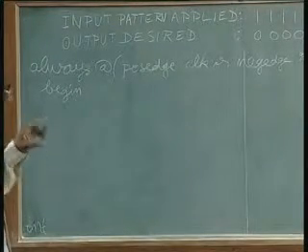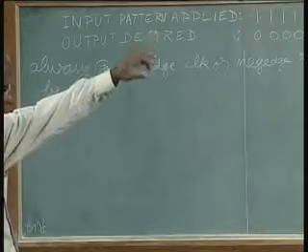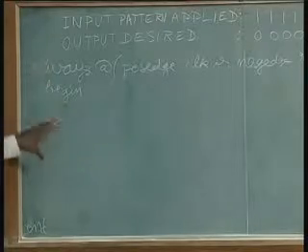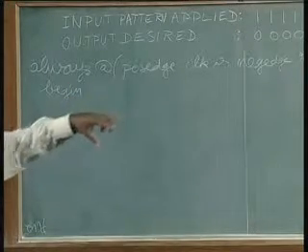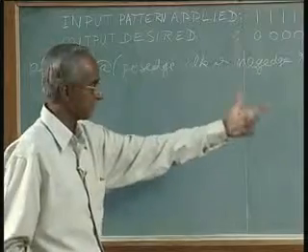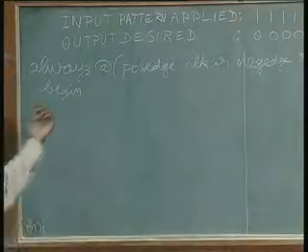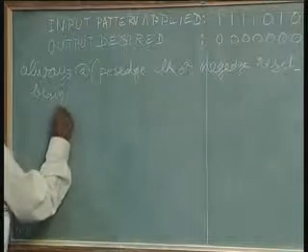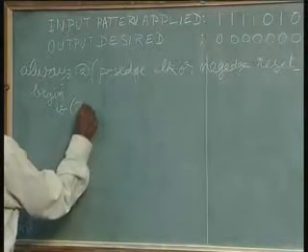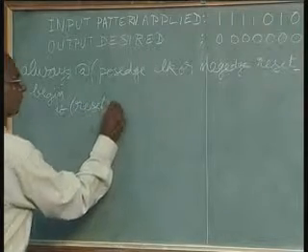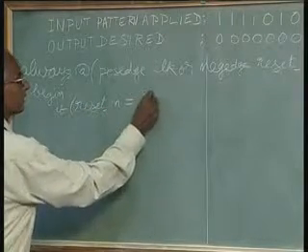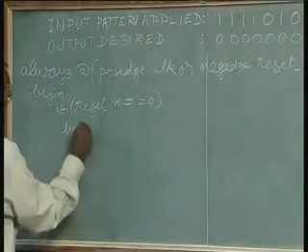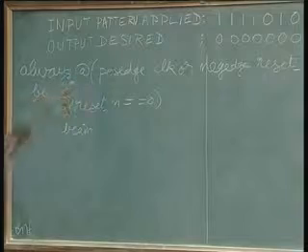Now what we have seen is we have to account for 4 states, 0 through 3. First what we have to do is, the reset signal is not shown there, but I have incorporated it in the program. So first thing we have to do is, if reset is encountered, what we have to do is, there are 2 outputs mind you, out as well as state.